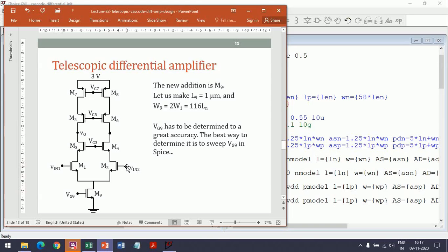We just have to make sure that these voltages are within that range. We can put any value you want within that range. It is up to you. Alright. I have taken 1 volt because it's just a nice clean simple number. But in fact you should find the ICMR for this circuit. I have not found it here. But you know how to find it. You go back and look at the differential amplifier lectures. You can find the ICMR and then you make sure that these two voltages are within that range.